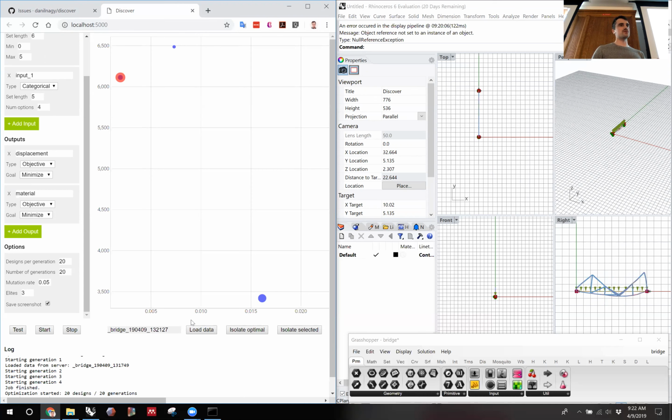And so some intuition for that is basically if you run the optimization and you're not getting enough variation, so how do we know if we're not getting enough variation? We might see convergence too quickly on a design that seems to us intuitively to be suboptimal. You're never going to really know, right? That's the whole point of using these tools. You don't know what the optimal design is. But you might see that within a few generations, it converges on something, it stops exploring other options and it really just fixates on this design that looks not that great. So then say, okay, we're not getting enough variation.